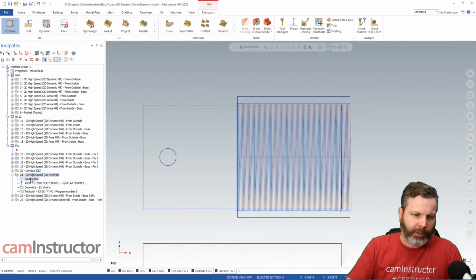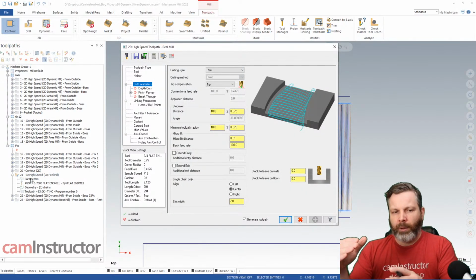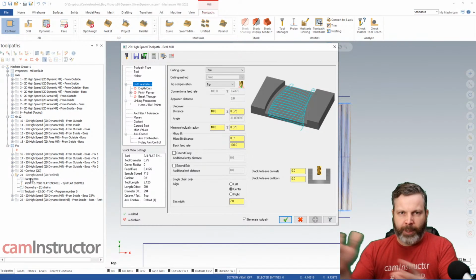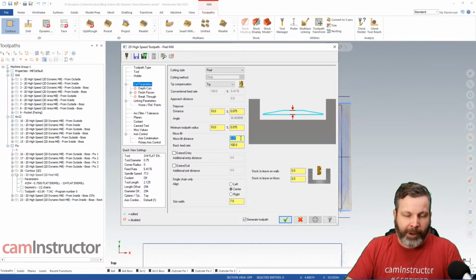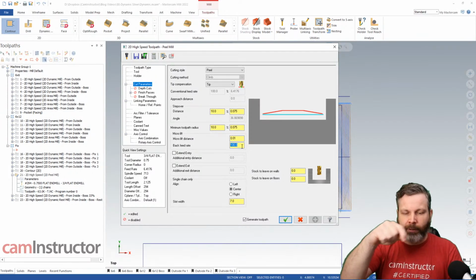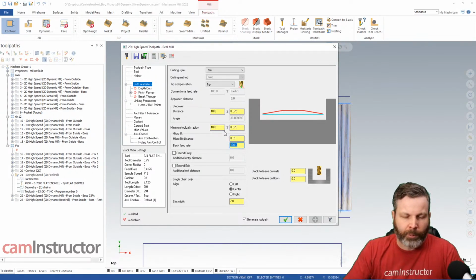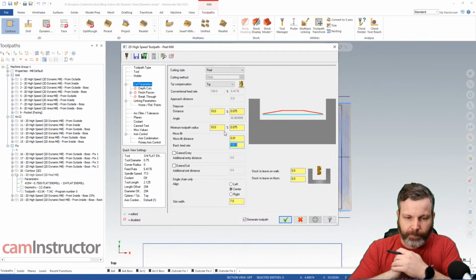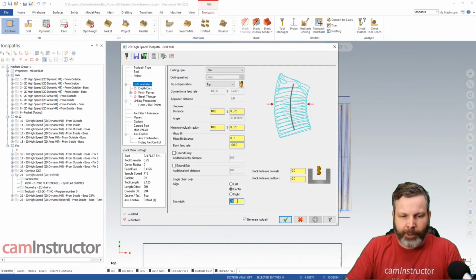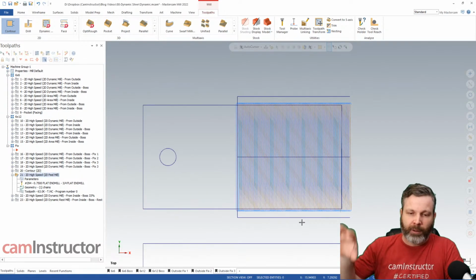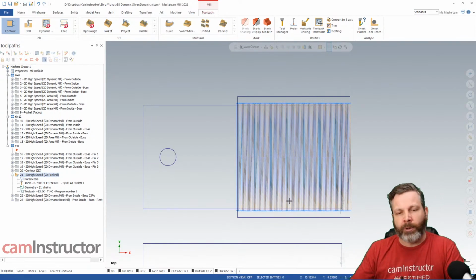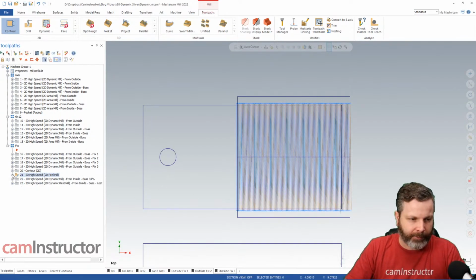Okay, I didn't have to calculate how many step overs given how far past the line I wanted to calculate. I've also got the option here for micro lifts and repositions. Instead of retract, rapid, over and down, I can control it with micro lifts, so that's an added benefit. With this one, it's easy for me to change the width as well. I can extend or shorten if needed. So peel mill, another good idea to chop off that long side of the part in order to get dynamic mill to work better on the other half.